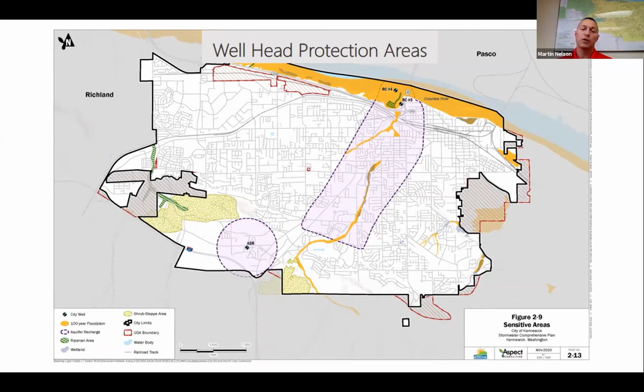The southwest corner, we do have an ASR. It's a 1,000-foot deep well that we store water in. So we pump and treat water and stick it in a big hole in the ground. And then we suck it back out to modulate flows. But you have to plan your project accordingly.